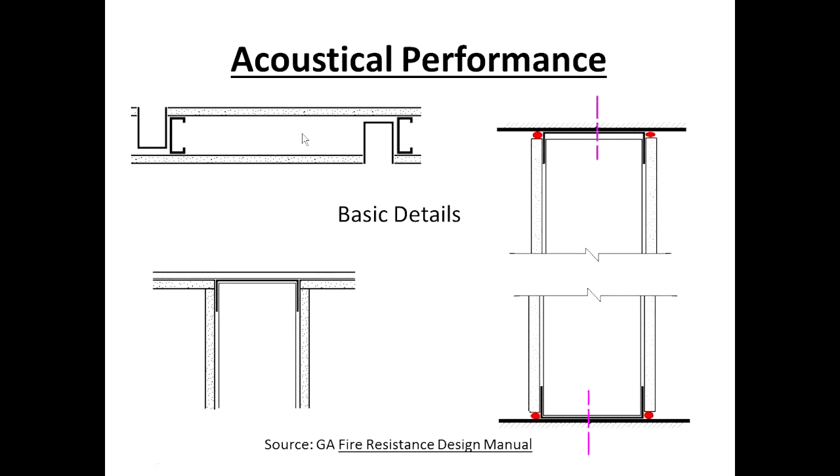Coming over here, we have electrical boxes. The minute you put an electrical box in a sound rated partition, you impact the sound performance. And you would never want to put outlet boxes back to back, nor would you want to put outlet boxes in the same stud cavity. So what you're looking at in this detail is there's a box here, here's a box 1 stud cavity over. What I'm not showing in this detail is you should put what's called an acoustical pad that totally encapsulates that outlet box. So you're totally trying to seal that box from any sound coming through.